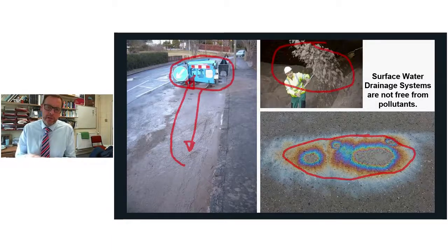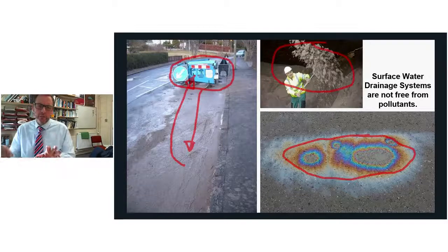Where they're most significant is where you have vehicles stopping, accelerating and turning, and where you get that most is big roundabouts and traffic light control junctions. So they tend to be the most polluted parts of the city in terms of surface water runoff. And again, all three of these things and more, with separate systems, make their way to urban watercourses and have an impact.